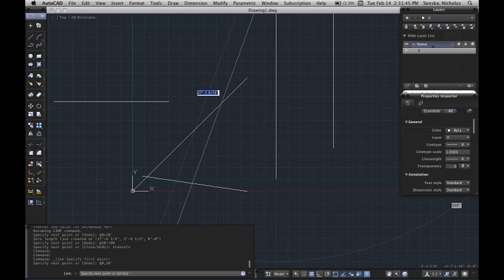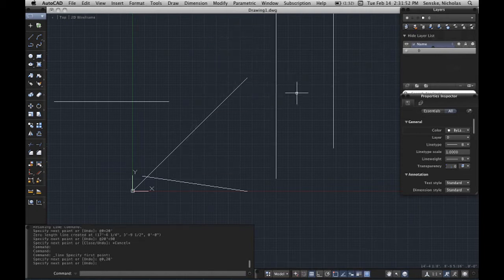So there are lots of different ways to get a measured point in space. If you type it in, it's actually the XY off your point. If you don't put the @, it's the real XY. If you put the @, it's the relative XY. Okay. And then lastly.